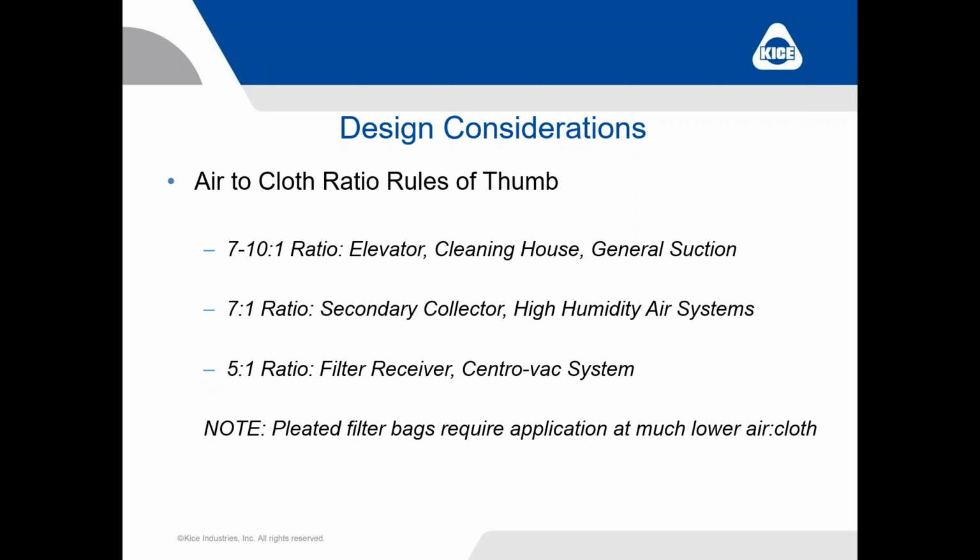But if you do use pleated filter bags, or pleated filter cartridges as a lot of people call them, those have to be applied at a much lower air-to-cloth to be effective and to have any kind of good life expectancy. So if you are working with pleated cartridges, you can effectively cut the numbers you see here in half or even much more to gauge where you are with your filter system.